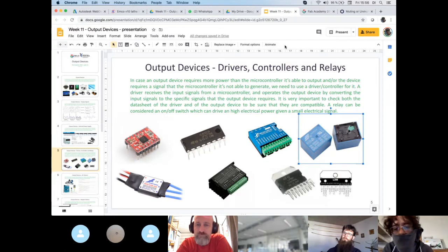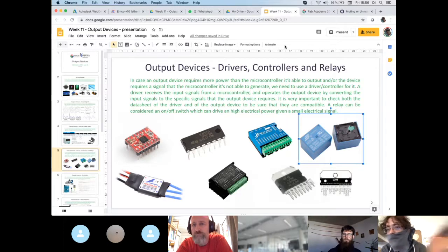And this space is usually a void or some kind of isolating thing that will never allow the coil to touch, of course, the other circuit. They are not proposed to protect the device that controls from the things that are being controlled. In the solid-state relay, I use them, for example, to drive the heaters of my big printer. Actually, the electronics inside is rather similar to a giant MOSFET.